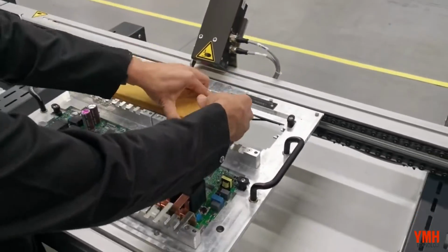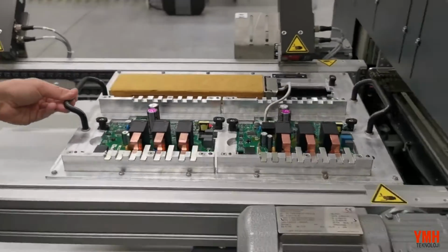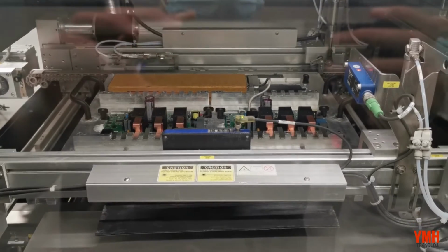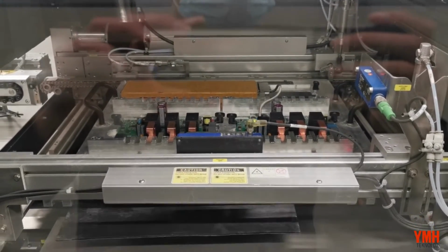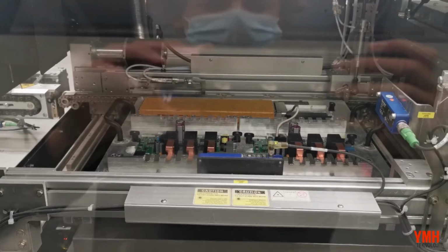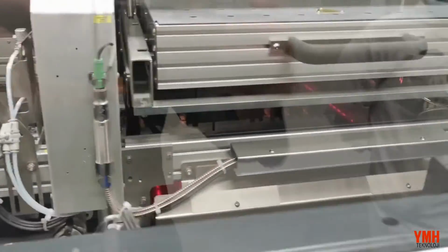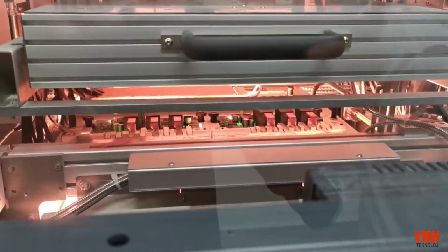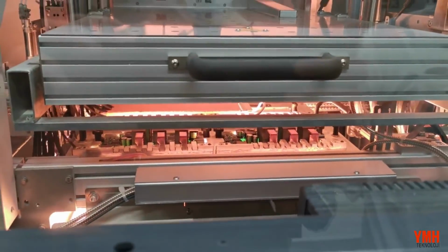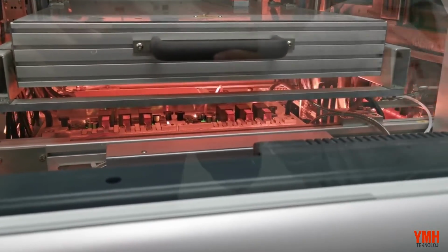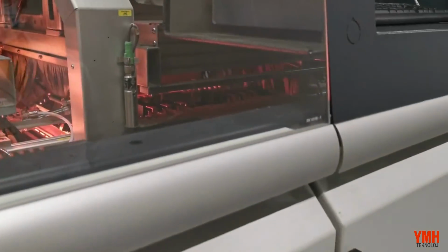Now put the profiler and profile board into the selective solder machine. Please make sure to use a thermal shield if necessary. In this video, we are displaying one example of profiling a selective solder process in a selective solder machine. Your machine may be different than this example and present different challenges with handling the profiler. It is important to carefully verify that there are no mechanical or other interferences to prevent you from profiling your selective solder process. On this video, you will see the profiler being carried on the same board pallet as the profiling board.